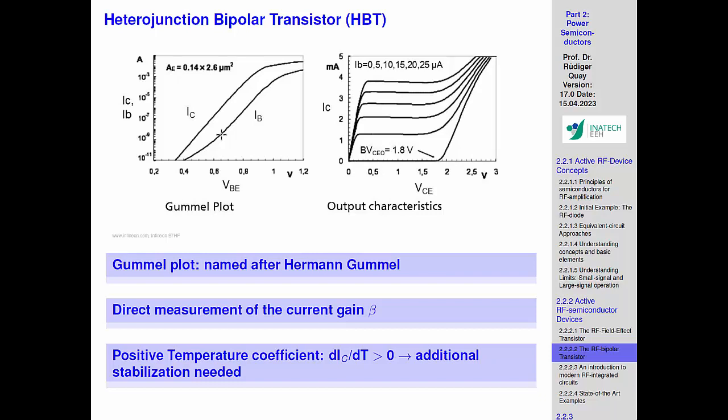And that's a lot of current amplification. You get a very high amount of current amplification through this additional contribution from the diffusion part, so not just field-controlled carriers, but also diffusion-controlled carriers, which enable a much better current flow because the electrons want to leave the emitter and just need a slight kick to go up there.